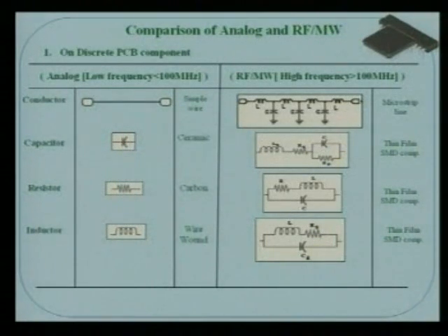because this tells you that suppose you have a simple wire and you are giving an AC signal. Have you ever thought that if the input is A sin omega t, then my output will not be simply B sin omega t or B cos omega t? You will always assume that my frequency is unchanged because it is a simple wire. But in case of lumped parameter or distributed, or transmission line models, when the component size is comparable to the wavelength, then what happens?